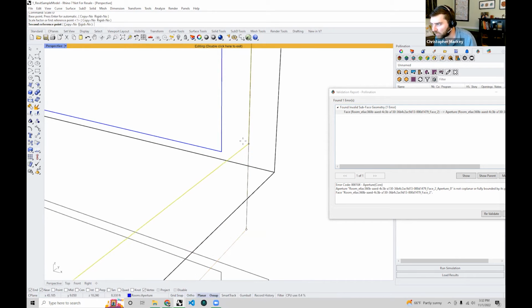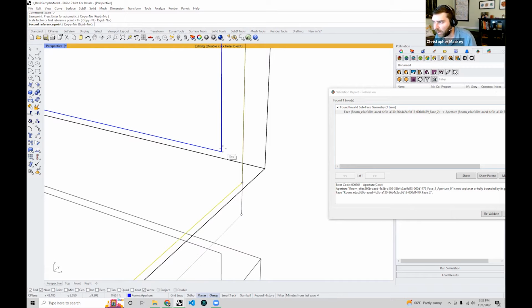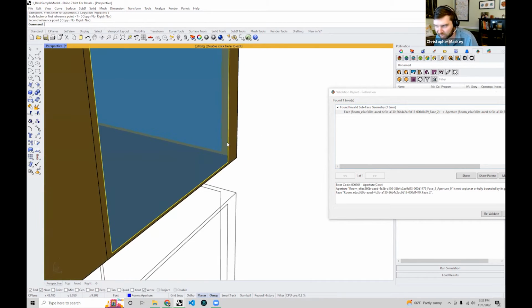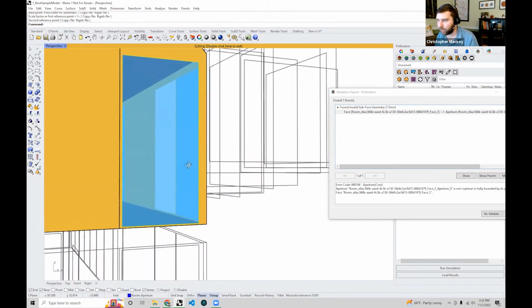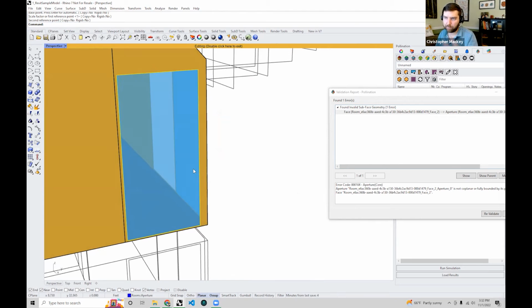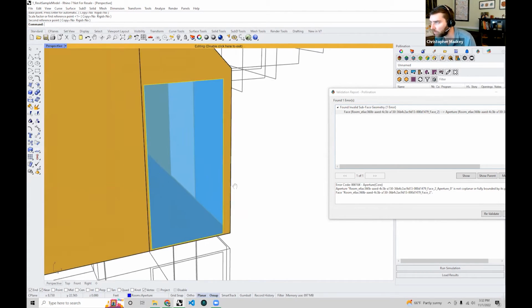And then I basically want to snap it to this height right here of this other adjacent window, right? Snapping to that endpoint. And you can see it's scaling the whole window in this one dimension. So if I click on that right now, it has scaled this window in just the vertical dimension, just in that dimension that I selected, such that now it's basically in plane with that parent face. And I've fixed now this geometry problem that I have with the model.